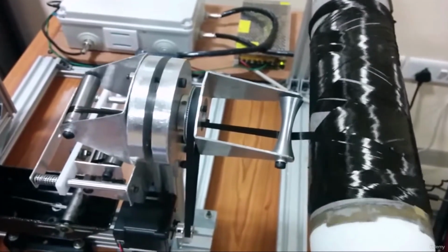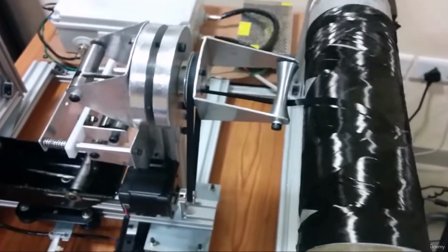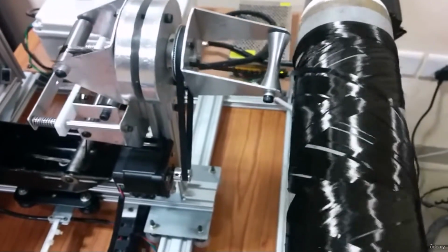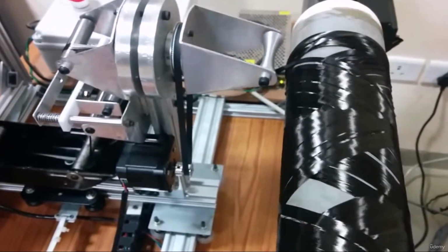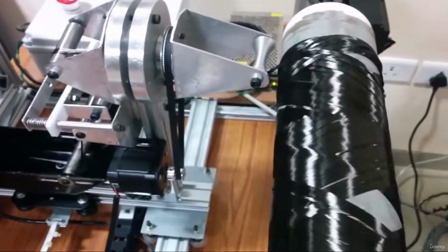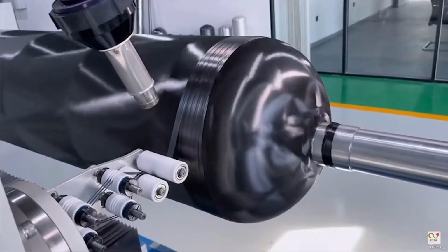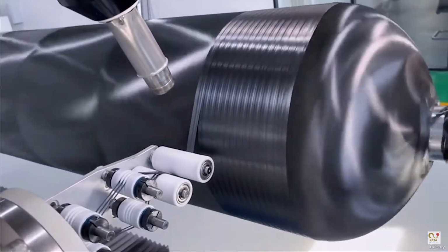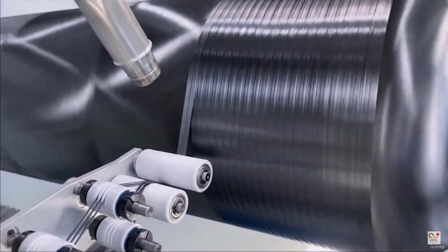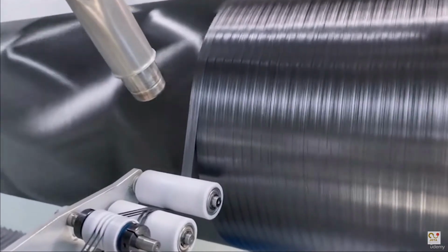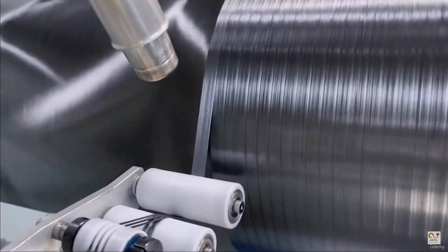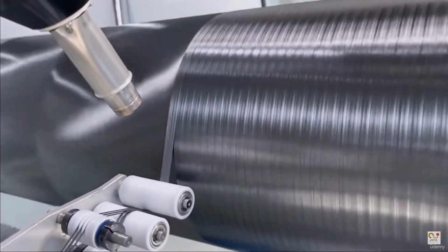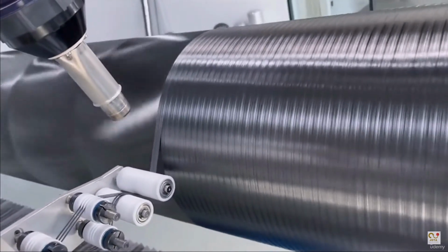network of fibers. As far as the advantages of filament winding are concerned, this is a very fast and therefore economical way of laying material down. Resin content can be controlled by metering the resin onto each fiber. If you are using dry fibers, you can very effectively control the resin content. Fiber cost is minimized since there is no secondary process to convert fibers into fabric or something like that. The structural properties of the laminate can be very good since straight fibers can be laid into a complex pattern.